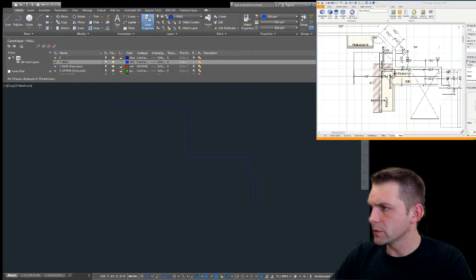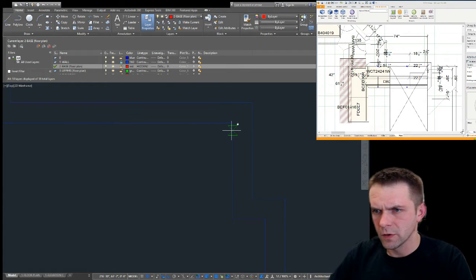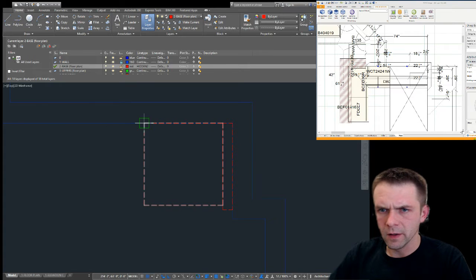We have a bulkhead, so right now we're just working on the floor plan, and we see that the first cabinet is going to be, so we do 24.875, and again this is going to be our filler, and then it's a 24 inch cabinet, rectangle, REC, line, 24, REC. So we select copy paste, then line again, or space for the repeat command.